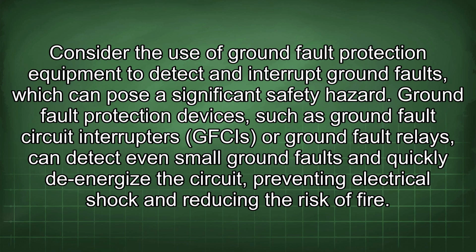Consider the use of ground fault protection equipment to detect and interrupt ground faults, which can pose a significant safety hazard. Ground fault protection devices, such as ground fault circuit interrupters (GFCIs) or ground fault relays, can detect even small ground faults and quickly de-energize the circuit, preventing electrical shock and reducing the risk of fire.